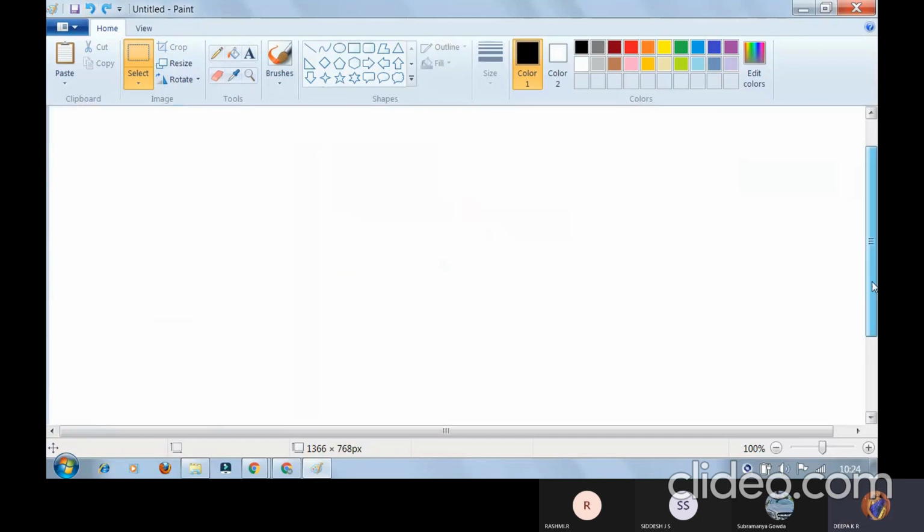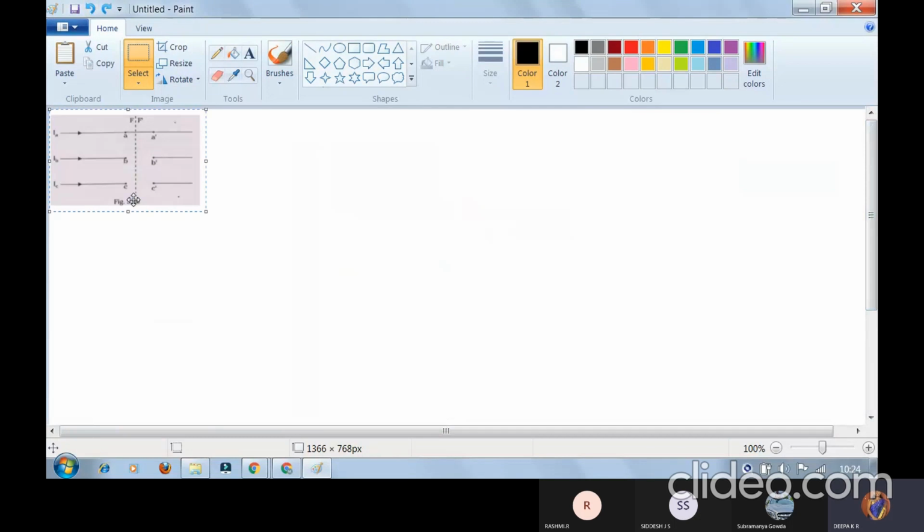Okay, so based on that, we'll write the conditions. From the diagram, it is very clear the current through conductor 2 and conductor 3 is 0, which means IB is 0. Similarly, IC is also 0. Due to this, current flows through the first conductor, but the voltage will become 0. That is, you can write it as VA A dash is equal to 0.